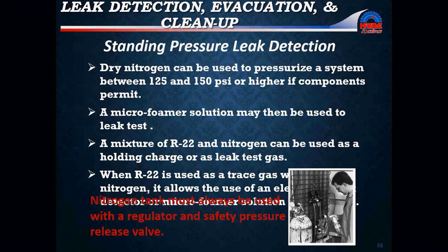A nitrogen tank must always be used with a regulator, and safety pressure relief valves should always be in use. Never use compressed air with refrigerants for leak checking. The approximately 20% oxygen in standard air could cause an explosive mixture when mixed with many refrigerants if exposed to a flame.